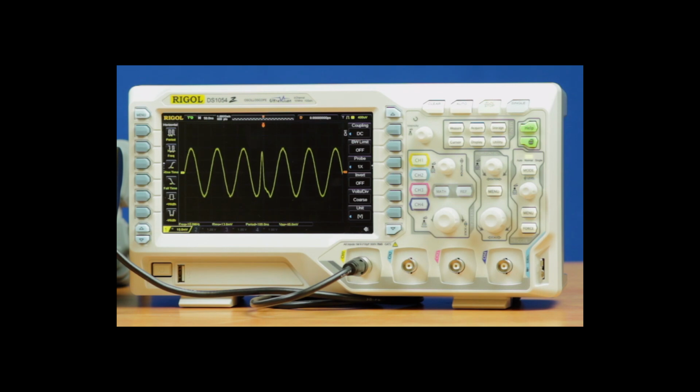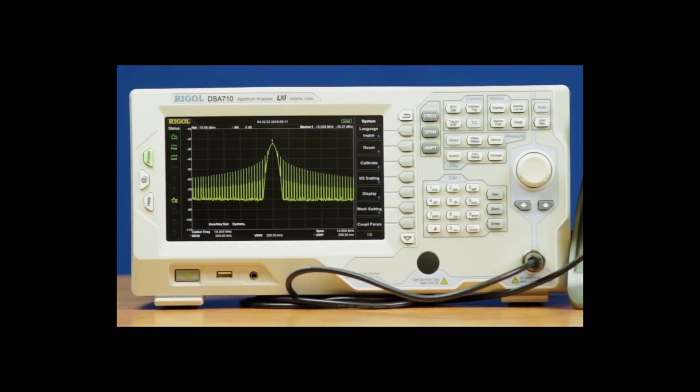Now let's look at the spectrum analyzer. The spectrum analyzer doesn't see anything about phase, right? So it just knows the frequency at the center, which is at 10 megahertz. But what's interesting is that in a phase modulation like this, due to the speed of those transitions, you're getting artifacts at other nearby frequencies. And that's what those tails are to the left and the right of the spectrum analyzer. You can see power in adjacent frequencies caused by the quick 180 degree phase adjustments.